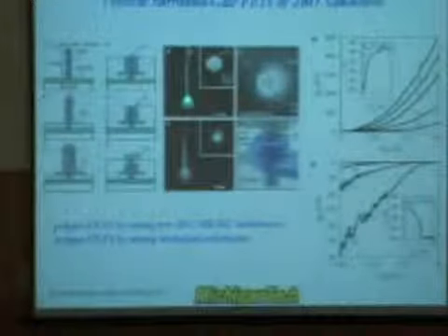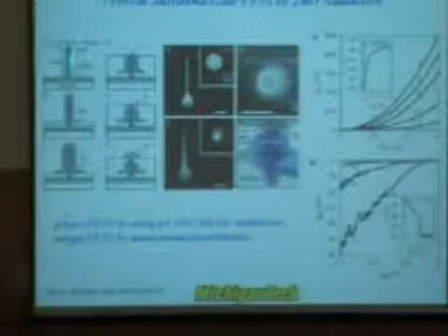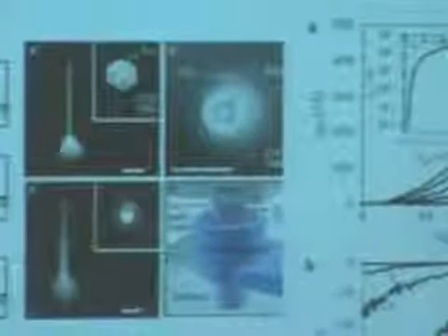So for instance, if you put one piece of the zinc oxide nanowires here, right? And you coat all of them with oxide, and then go through all the lithography techniques. You put down your so-called drain, source, and gate electrode like this: drain electrode, source electrode, which is the substrate, and the so-called surround gate. You actually can make the so-called vertical surround-gate field effect transistor, right? So it's very interesting work going on here.